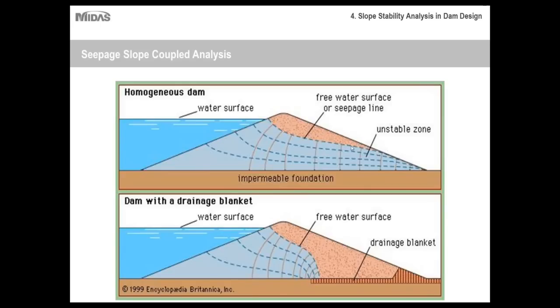So depending on just the strength of your materials, the level of seepage, the stability of this side of the dam can be compromised. Whereas if you have implemented a drainage blanket, as shown here, the flow path changes very significantly to the point where all the water is seeping down into the drain and the water is being safely drained out the other side, while maintaining the structural integrity of this slope here. So that's why sometimes a clay core is used just to block the seepage or to slow it down, or a drainage blanket or a drainage pipe is included, just to change the direction of the water. So that's one solution that could be created for your dam.